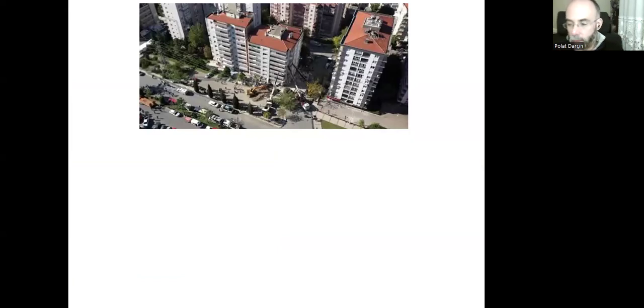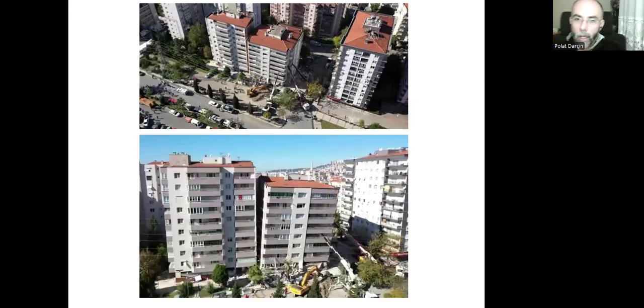That's from Izmir earthquake. It was something like 2016, 2018 or something. There are two adjacent buildings, two separate buildings, and they did this seismic gap. This building is intact, but this other has structural damage. It's not collapsed down yet, but it slightly moved and inclined like this.